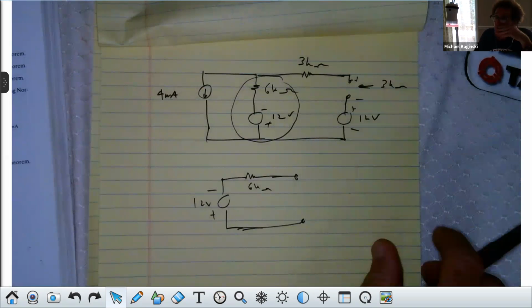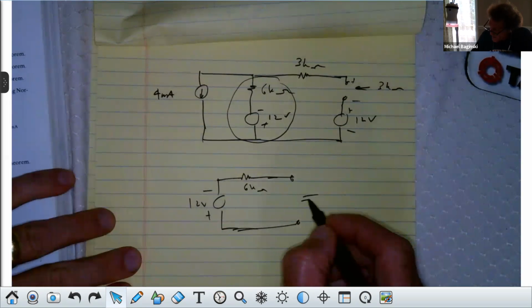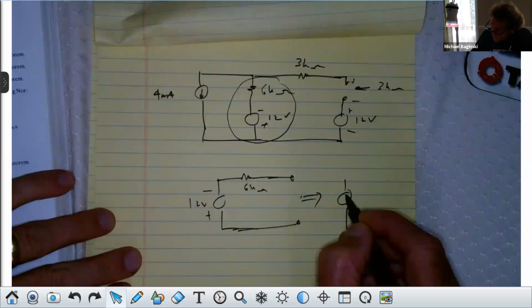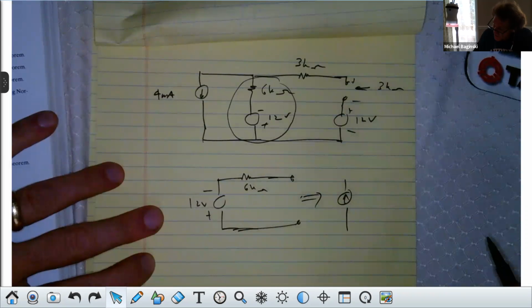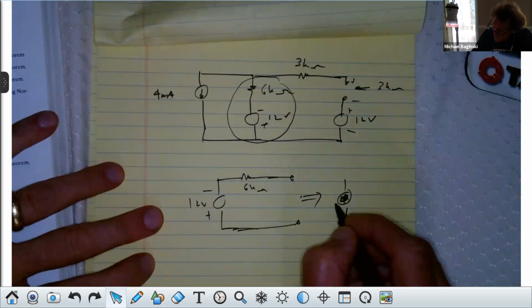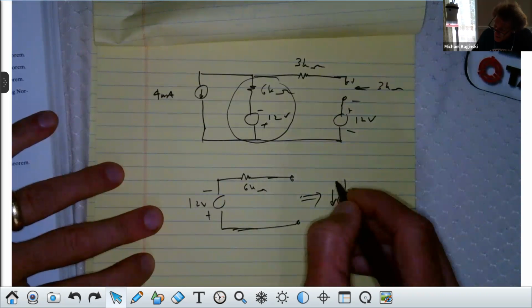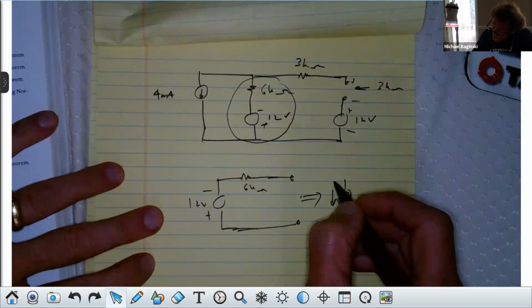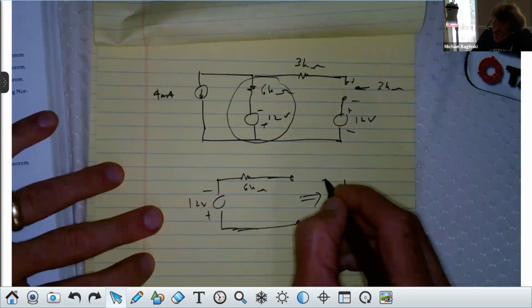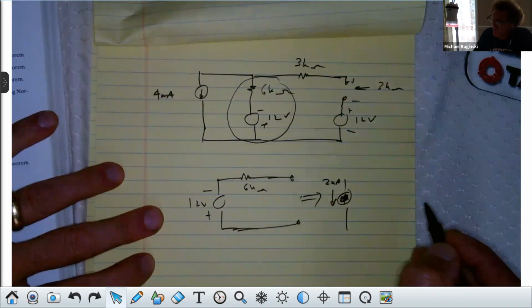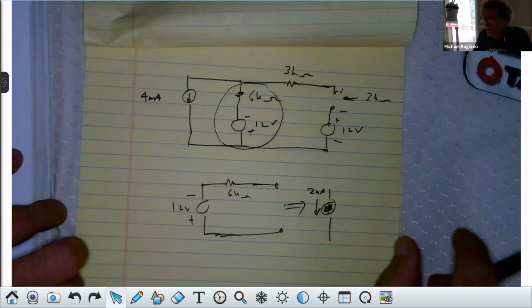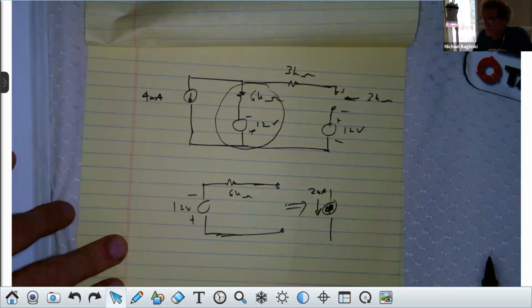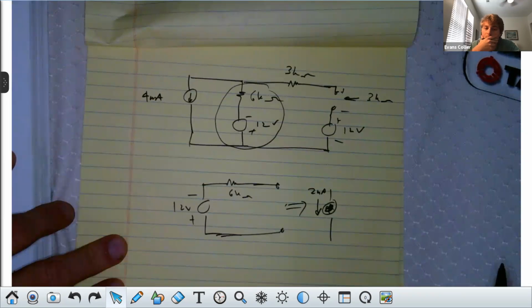Yeah. All right, what's that equal to? Well, isn't that equal to a current source, right? Where the current would be minus 12 divided by 6K, or the current really would be in this direction, right? It would be 12 over 6K, or 2 milliamps going down. Do you all see that? It's going in that direction. Can everybody see that, people? Okay. It's going down, right?